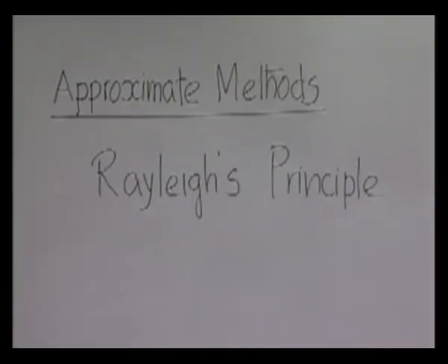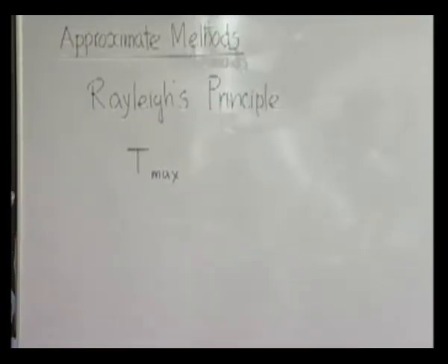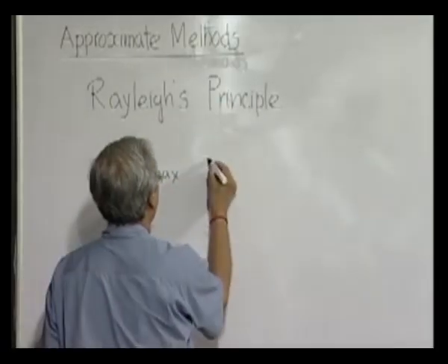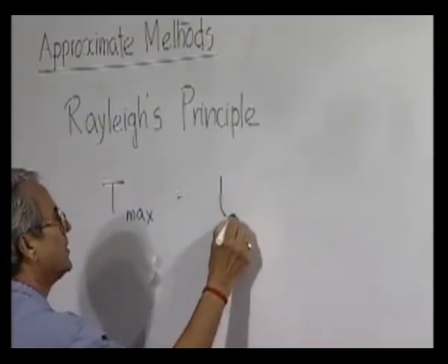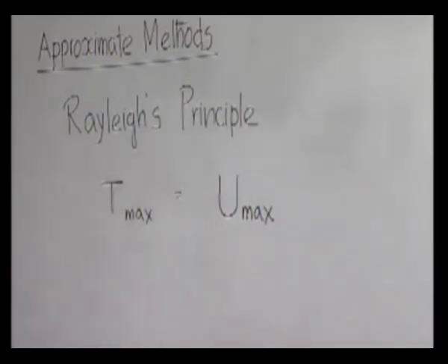that for an undamped system, in the steady state, the maximum kinetic energy during free vibration must be equal to the maximum potential energy, which in case of elastic bodies is predominantly the strain energy involved.